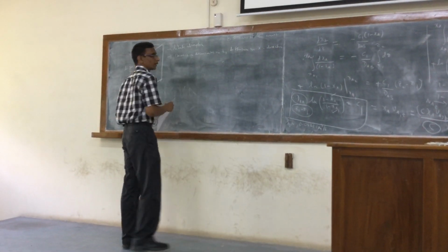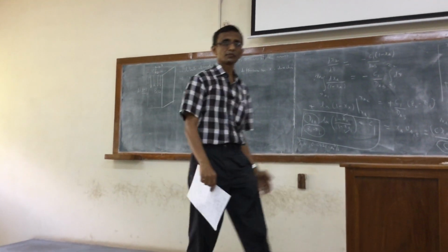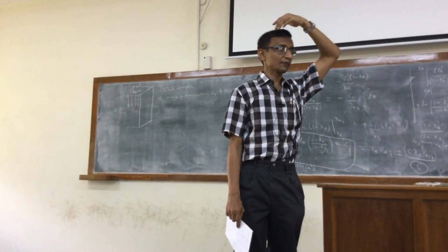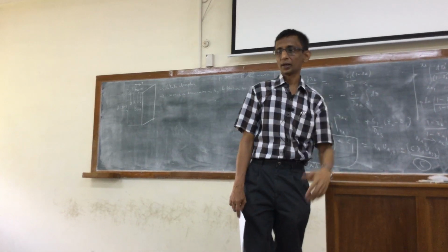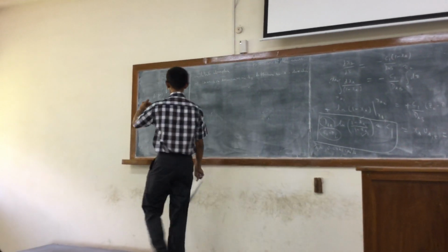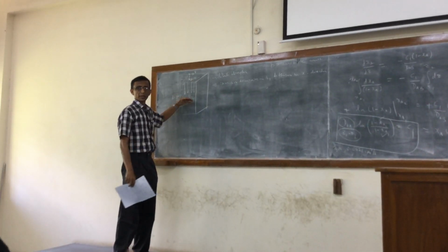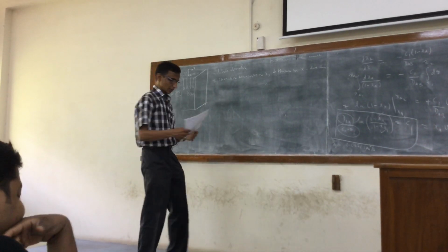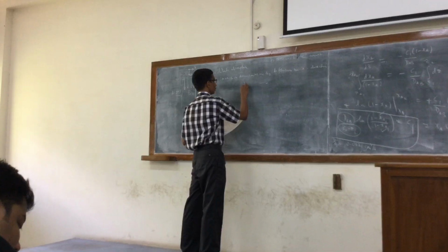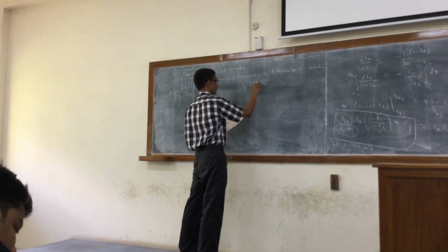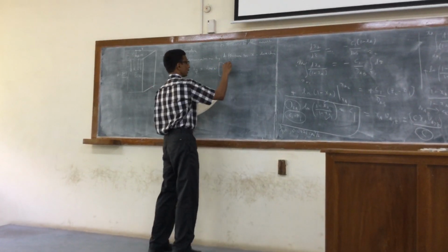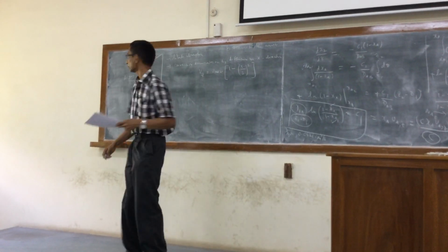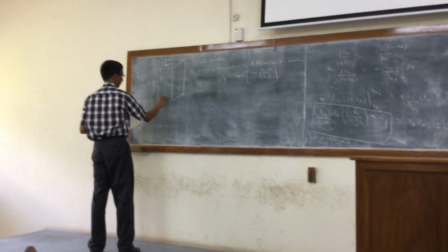The flow is in the Z direction due to convection, the forced convection because of gravity, pressure difference and so on. We already have the formula for the velocity profile, right? But we assume the gas diffusion effects dominate in the X direction. The convective effects can be assumed to be negligible in the X direction, right? So that is a basic assumption. We know that v_z is v_max times (1 minus X over delta) the whole square. We've already got this. The delta is the thickness of the film.